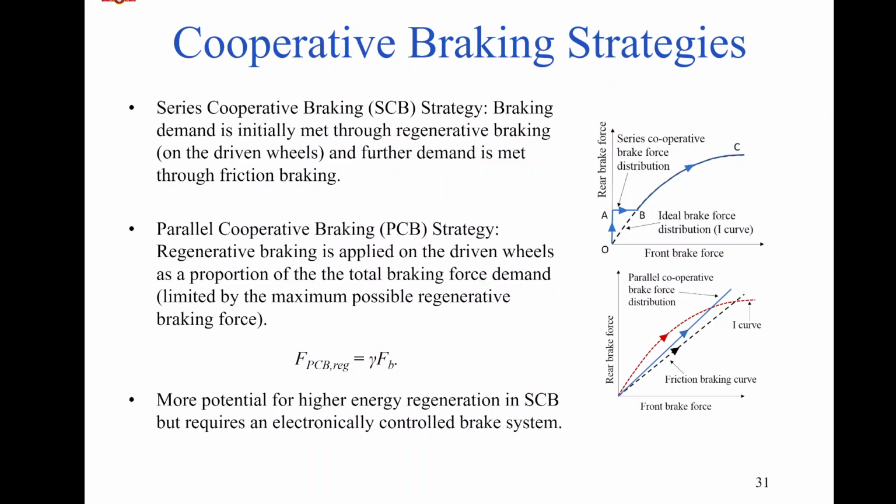In city driving conditions on shorter ranges, it by and large acts like a pure electric vehicle, but when you need a vehicle which can take you long distances without much of an issue, a strong hybrid gives a larger flexibility in that sense. Hybrids do allow you to operate the motors as well as the engines in their best region of operation.